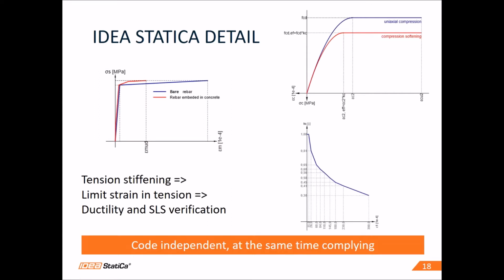As we are speaking about this and why we implemented such advanced things, it is that we want to comply not with just the static but also the kinematic formula, and thus we can capture the real mode of failure to solve ductility examples. And of course, this enables us to do the SLS checks.